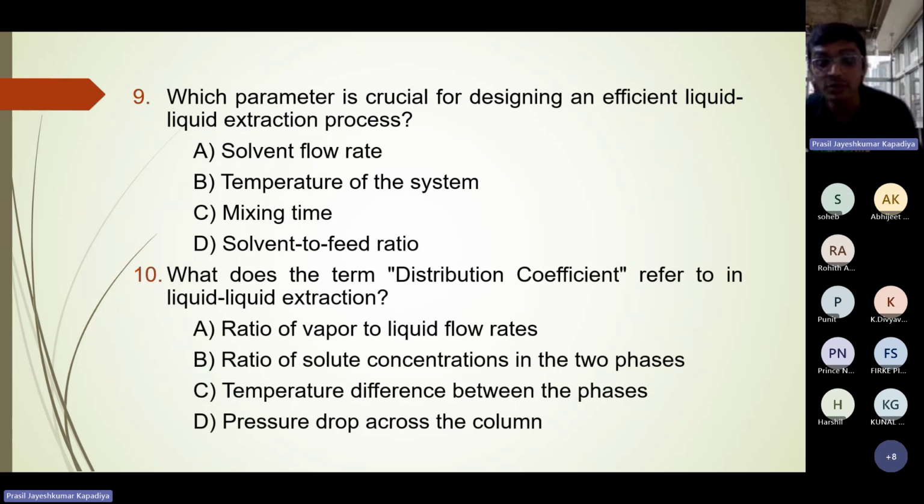Next, what does the term distribution coefficient refer to in liquid extraction? Have you studied this distribution coefficient? Ratio of solute concentration in two phases. It is not exactly like relative volatility, but it is y by x: solute in extract phase divided by solute in raffinate phase. The higher the distribution coefficient, the greater the extraction. Correct?